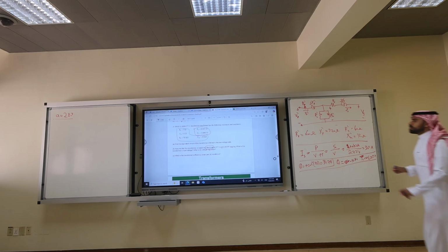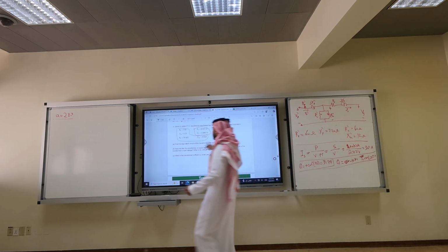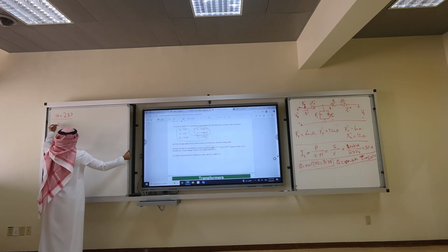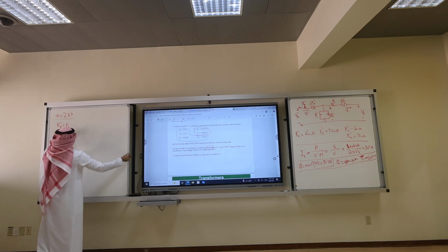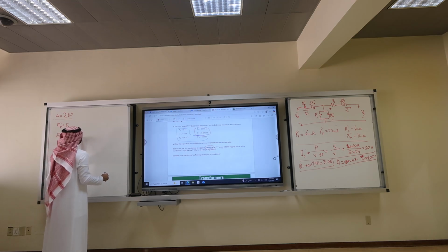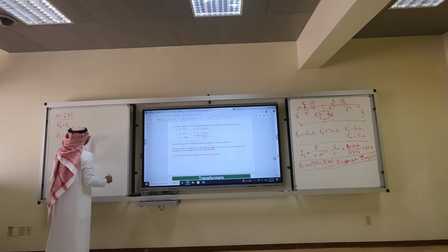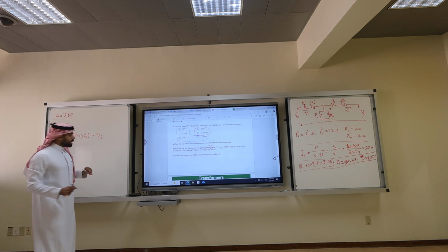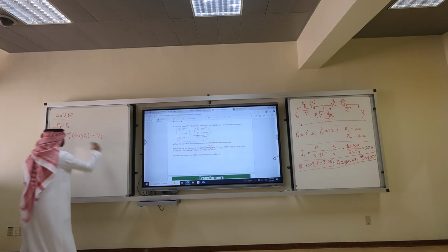Let's do the KVL. You will have EP prime or ES. So let's use ES, voltage rise, minus IS times RS plus JXS, minus VS. Doesn't it say IS instead of IS prime? You are right, that is IS, not IS prime.